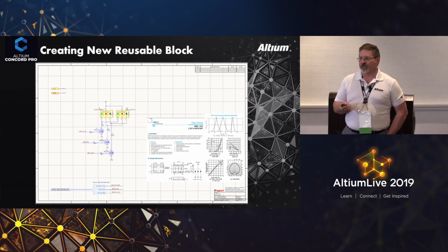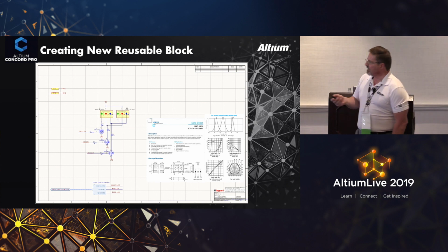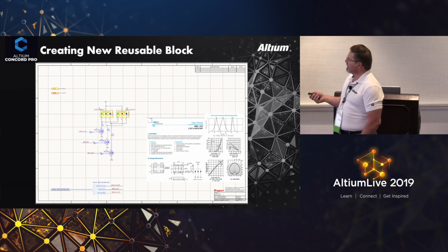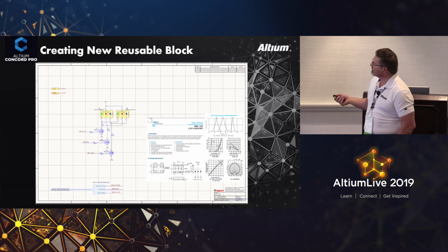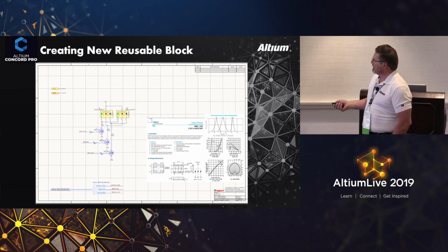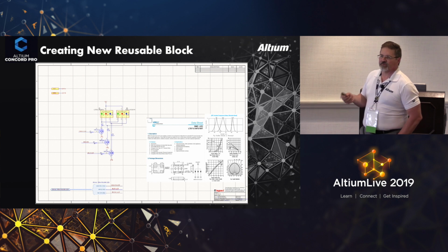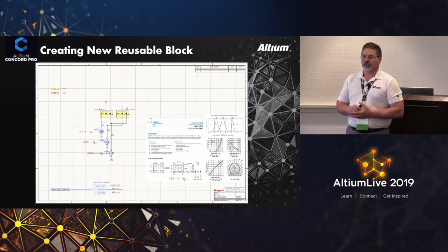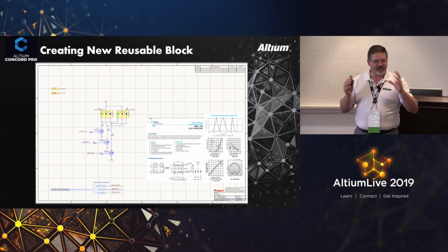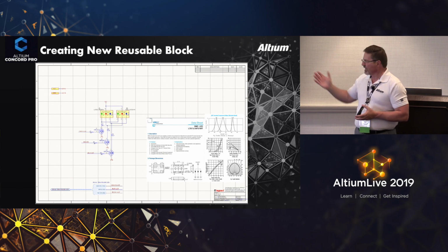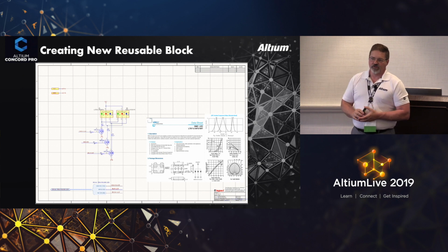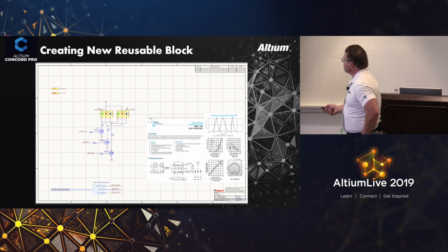This is very, very helpful. In here you have an off-page port, for example, which goes to a single net. Here you're able to set up an off-page connection with multiple nets, however many nets you would like. They go into that single harness, and then they go off the page from there. This is a really cool tool. I would highly recommend learning this because it is really great.